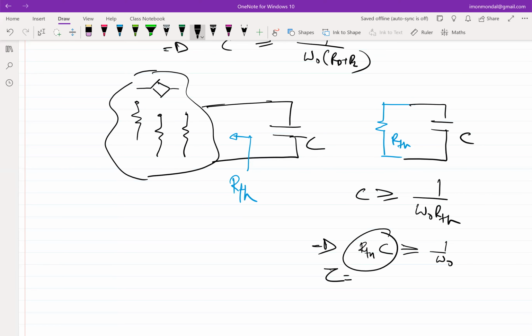But when you are doing a design on the fly, you don't want to disrupt your thought process and always go back and find out what the conditions will be. So you should be able to look at the circuit network and figure out the constraint intuitively. And given any set of networks, assuming again it's a first order network, it should be pretty straightforward to figure out what the values of the capacitance should be, if we want the capacitor to act as a short circuit. And the hack is find out the Thevenin equivalent and then ensure that the time constant is much greater than something. What is something in this case? It is 1 over omega naught. Okay. Any questions?